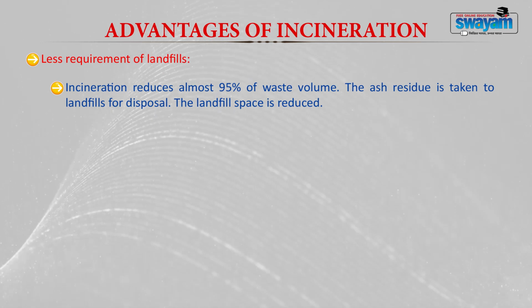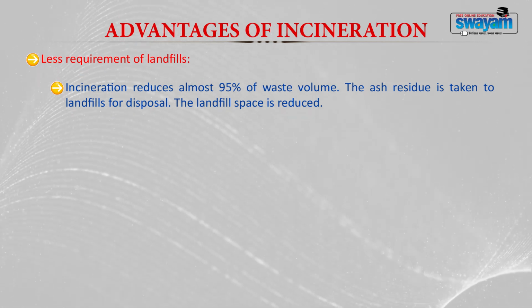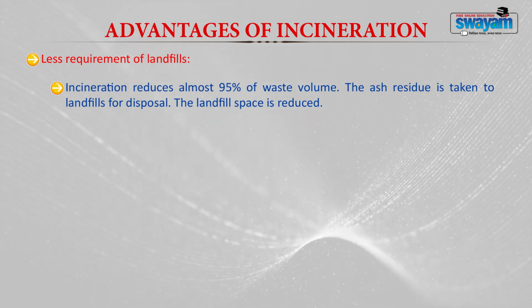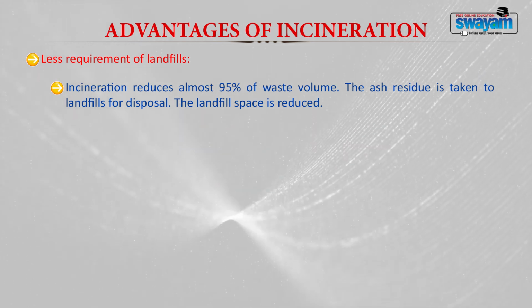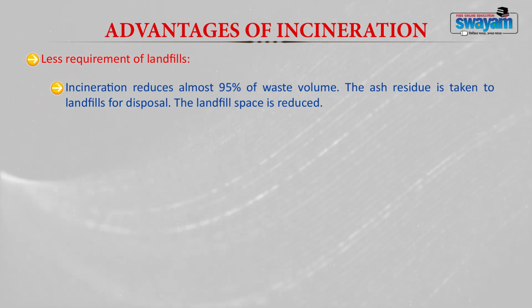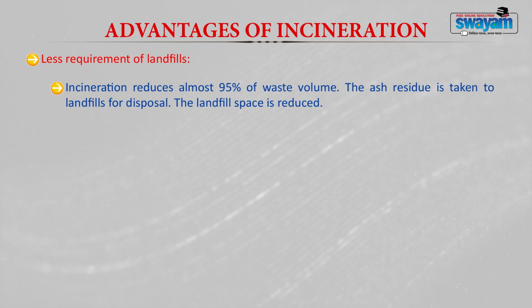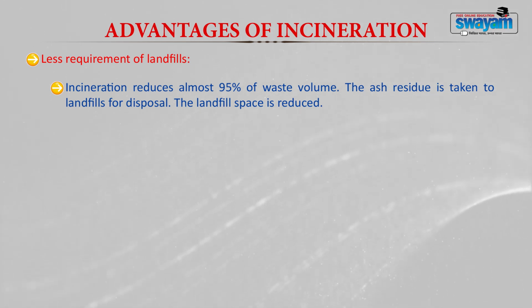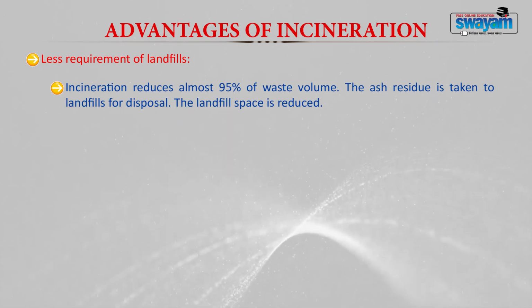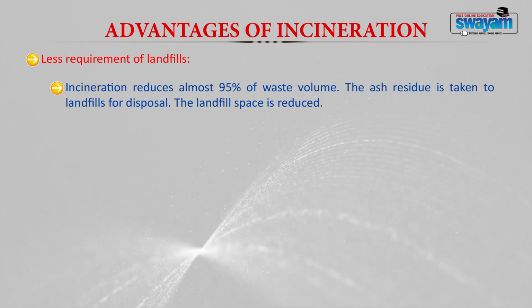As a result, the inert residue that is left out is very small, and when it is disposed of in the landfill, it reduces the space requirement. So, incineration reduces almost 95% of waste volume, and the ash that is left out is disposed of into the landfill. Since it is a small quantity, just 10% of the waste, it reduces the overall space of the landfill.